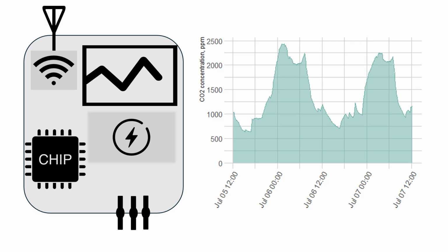We can use indoor climate monitors to keep track of different components of the indoor environment like temperature, humidity, particulate matter, CO2 levels. CO2 levels can be used as an indicator of how good ventilation is in a space. When you have CO2 levels consistently over 1000 parts per million, that suggests that some corrective actions may be quickly needed. Like you can see in this plot, this is for a bedroom. The CO2 levels get over 2000 parts per million during both nights that we're monitoring. And hence, the bedroom ventilation seems inadequate. This is the kind of insight you can obtain from indoor environmental monitoring.